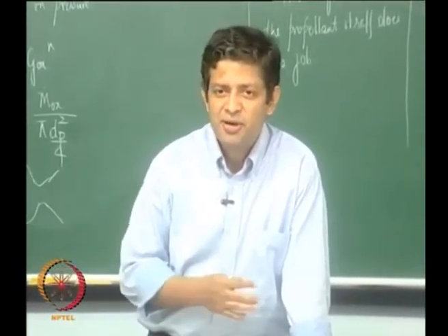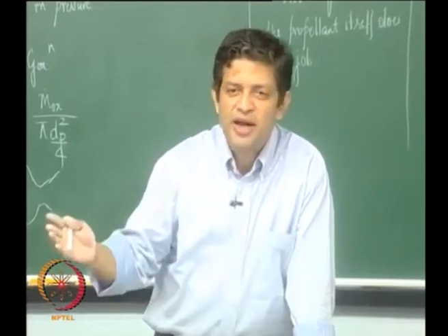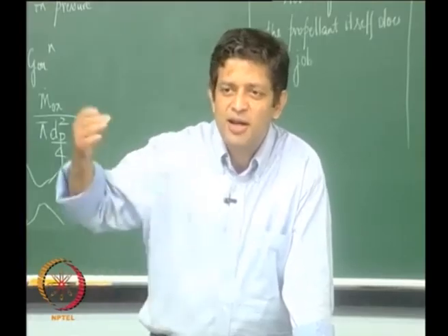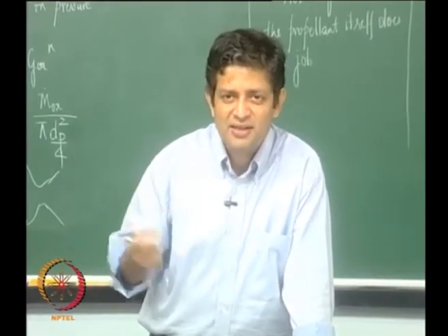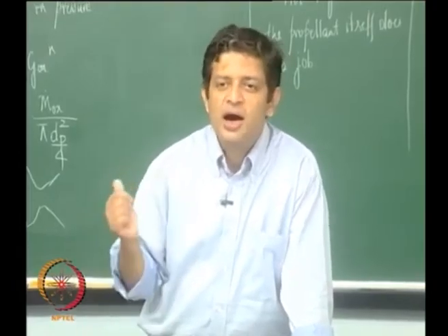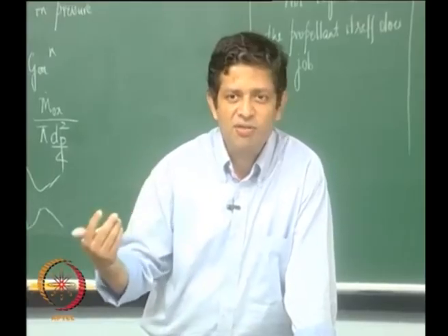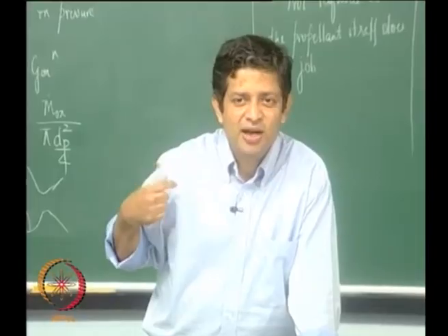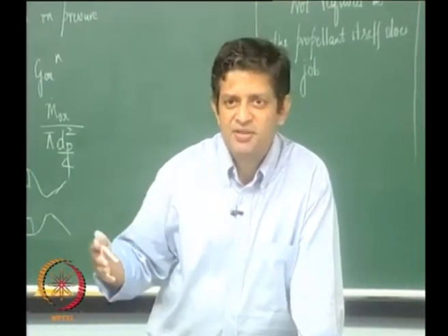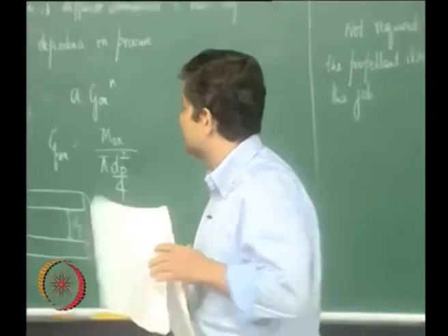If you remember, there also we said as you go from the head end to the nozzle end, the Reynolds number keeps increasing, the boundary layer thins, and therefore you could have erosive burning. The phenomenon is very similar here too. It is a strong function of the thickness of the boundary layer, and the boundary layer is dependent on the mass flux. So, that is why we have such a relationship.